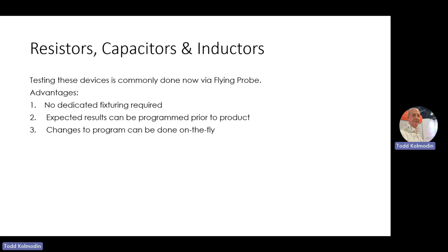And this worked fairly well, but it was also fairly unpredictable, depending on lamination cycles and heat. Trimming of the resistor could cause erroneous results. And we found a lot of times that just the heat of lamination caused the unpredictability. So trying to predict the resistor output after lamination cycles was difficult.